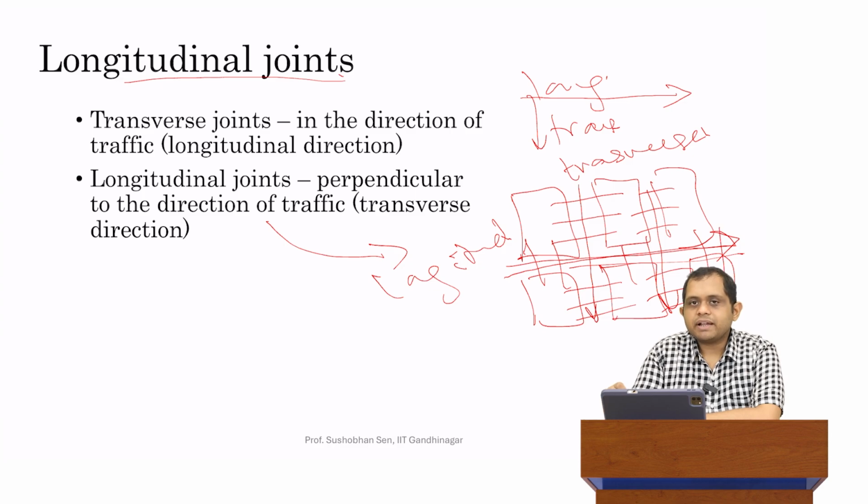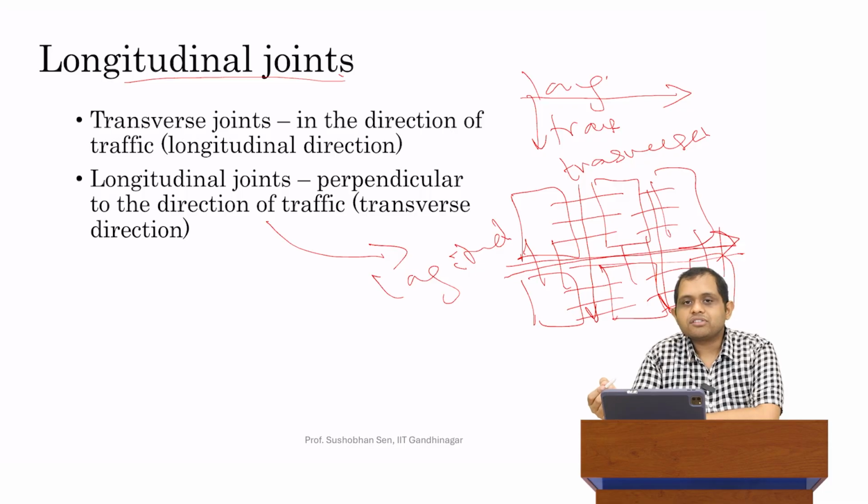It's not that steel cannot be applied over there. And it's not that those steel bars do not cause any load transfer. They actually do. It's just that we may not consider it in our analysis. It's not particularly important during the analysis to consider dowel bars, to consider these bars in between.